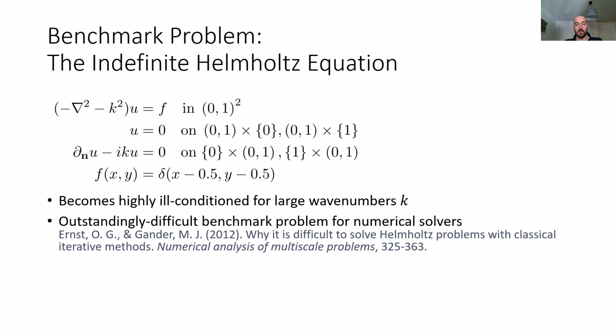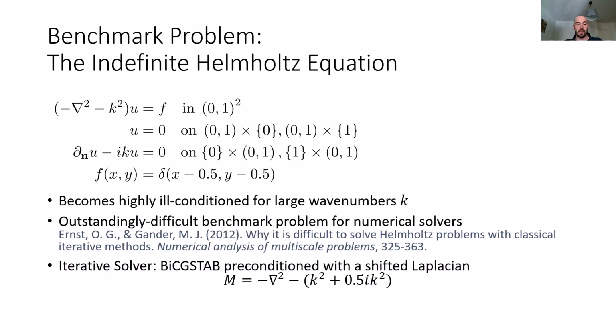For instance, this paper gives a good overview of why this problem is hard and what methods are available for it. To solve this equation, we apply a pretty standard iterative solver, BiCGStab, and we precondition this with a shifted Laplacian.